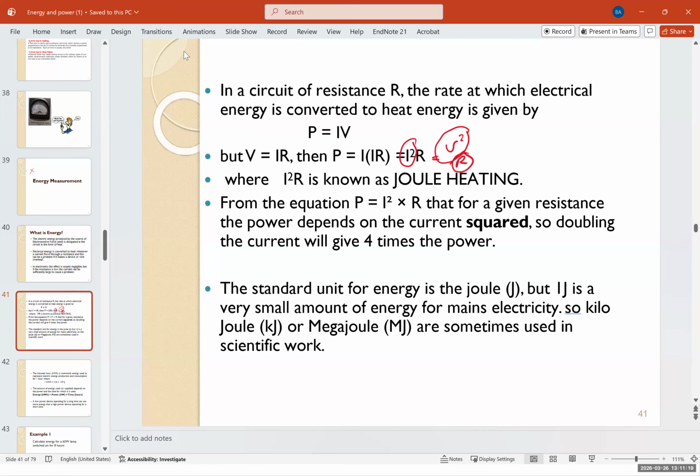And contrary to popular belief, the transmission lines are mainly made out of aluminum. They're not made out of copper, and they usually have a steel core. Aluminum has a higher resistance compared to copper, and the best conductor that we have right now is gold. Obviously, you don't want to have gold on your wires. If you had that, you're going to have everyone on one of these poles taking them down. And copper is very expensive, so mainly they use aluminum. Still, aluminum is expensive. In some places they take the lines down, melt them, and use them again.